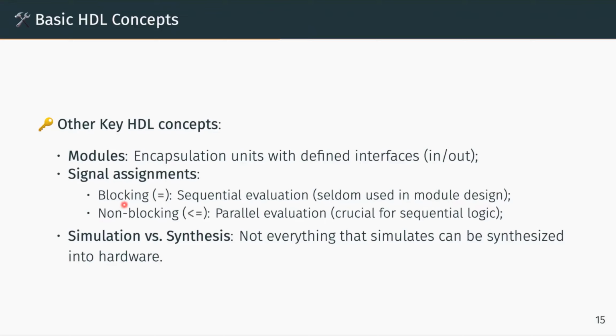And for writing HDL, one thing we need to be careful about is that there are blocking assignments and non-blocking assignments. This is very crucial for sequential logic design: we certainly do not want one operation to block another operation. They need to run in parallel in most cases, and that is non-blocking assignment. If we really want it to be sequential, mostly in the testbench, then they can be blocking. This needs to be kept in mind, as you may encounter it in the future.